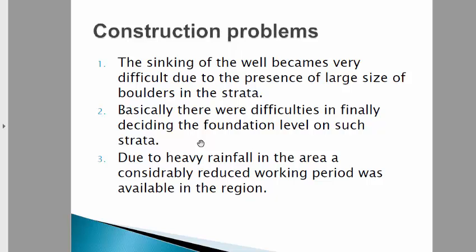It's also a very complicated case to decide the foundation level, at which level we decide the foundation, because the level of foundation decides how much load it can take easily and safely distribute from the deeper soil. The third problem is heavy rainfall in the area, which reduces the working period available in the region. Due to heavy rainfall there will be delay of the construction process.